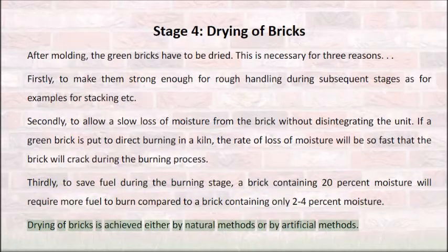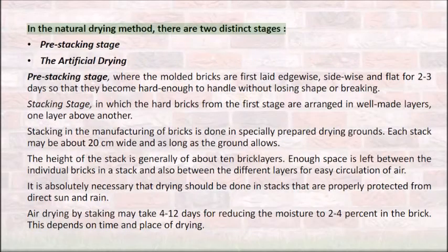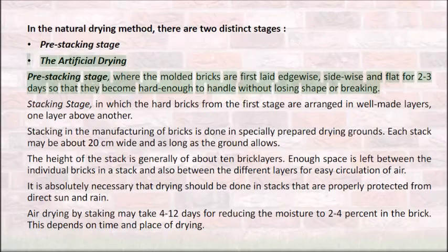Drying of bricks is achieved either by natural methods or by artificial methods. In the natural drying method, there are two distinct stages. Pre-stacking stage, where the molded bricks are first laid edgewise, sidewise and flat for 2 to 3 days so that they become hard enough to handle without losing shape or breaking.